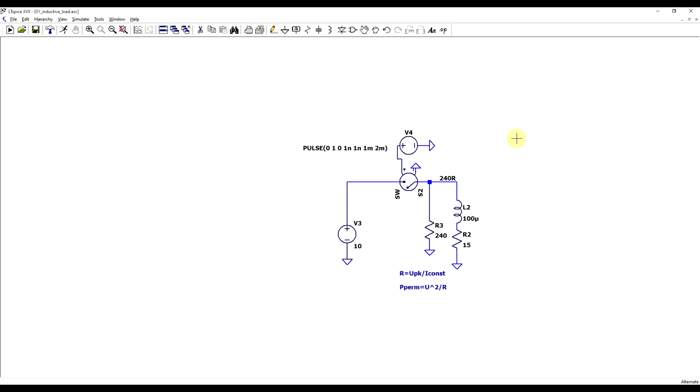but first in the simulator though. So starting off with the resistor only network, the resistor can be designed to give a specific peak reverse voltage if we know the current running through the load, and the downside of this method is the constant power draw that will occur. Final thing to keep in mind is that the resistor needs to be able to handle the peak power that gets dissipated during the turn-off phase.